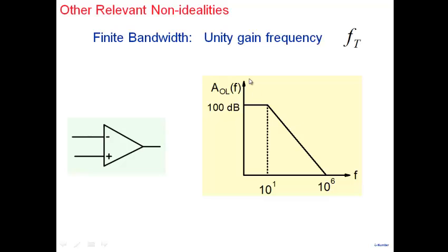So note that you probably thought that your op-amp is wide bandwidth. What is the bandwidth of your op-amp? The gain of your 741 op-amp may start falling at 10 hertz. 10 hertz is where it would start falling, right? And then gain keeps on falling. At 1 megahertz, the gain of your op-amp is 1, close to 1, right?